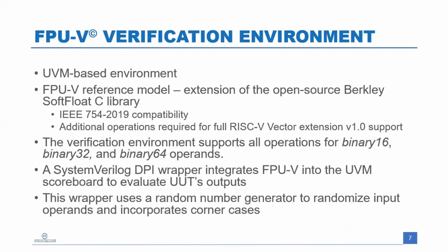As a complement of the actual design, we were also in parallel working on the verification environment. The reason is that, while we were generating the design, we wanted to check that the changes or modifications that we did are actually correct. So we started with something that is widely known, which is the Berkeley SoftFloat C library. But that library does not support all of the cases that are required for RISC-V vector computations.